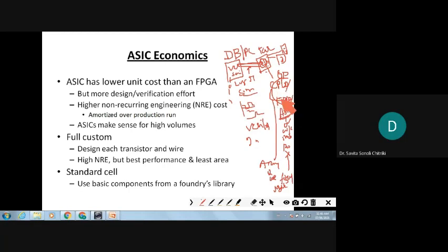The difference is that both have AND-OR arrays only; the capacity is less in CPLD, whereas in FPGA the capacity is more. Depending on the application, you can choose either CPLD or FPGA. So they are general purpose.